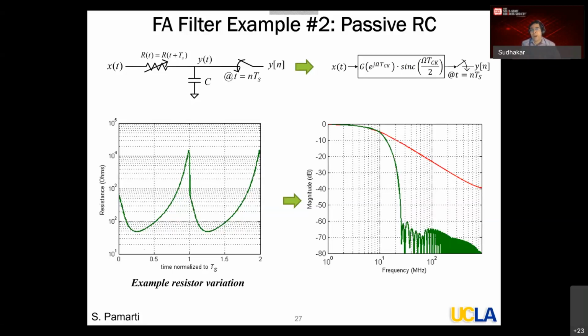This circuit, by definition, is going to be incredibly linear because you're not using the transistors in their linear mode of operation, where the nonlinearity is a concern for you. Furthermore, as you go to finer and finer technology nodes, switching the resistor is going to become easier and easier because of scaling. Transistors become smaller, they can switch faster, and so on and so forth. Okay, so I believe that this approach could be very, very attractive in a lot of different settings.